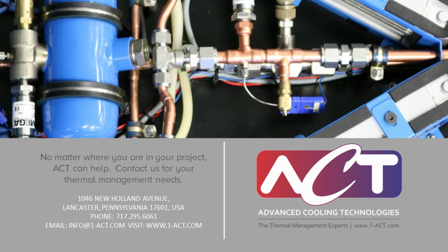And again, since it's a very well-established technology, the qualification testing is what we consider to be more a qualification by design. So with each new design, we will do the same thermal performance checks, maybe additional temperatures, powers, etc., to really define the performance of the extrusion selected. We'll maybe do some shock and vibration, burst pressure tests, just to verify where that envelope truly fails. But all things considered, once it's passed its qualification testing, you don't have to repeat it.